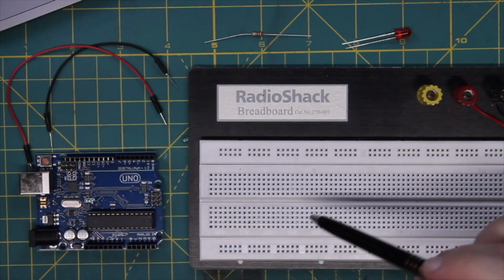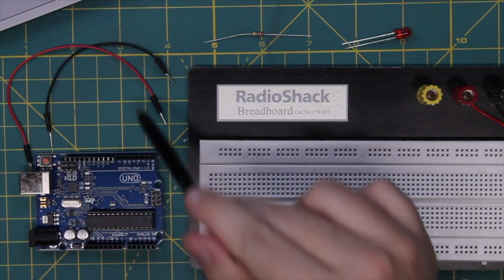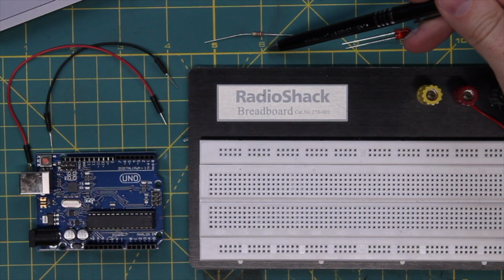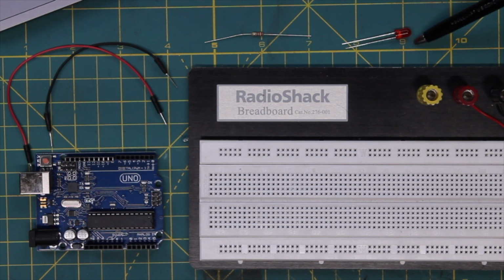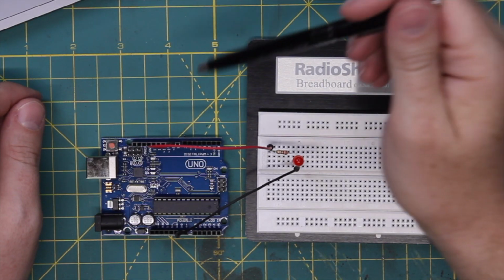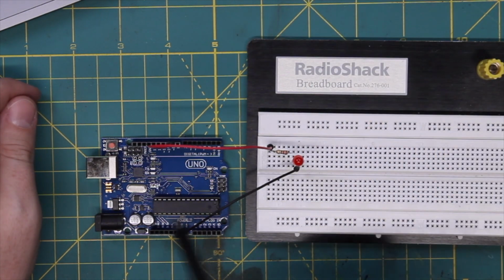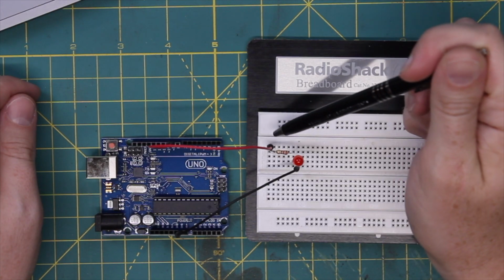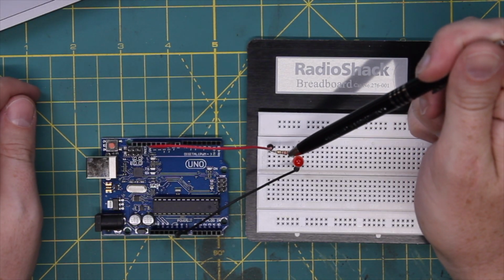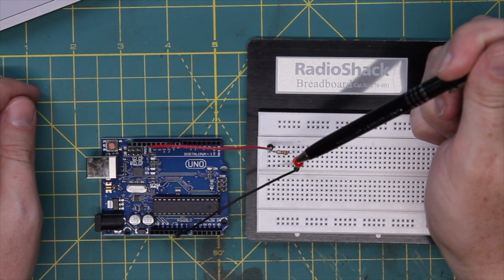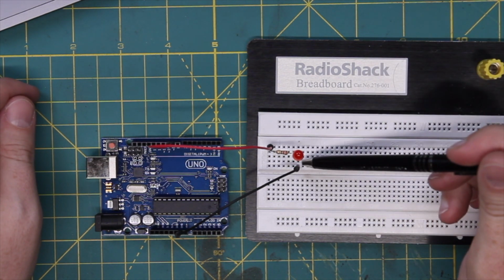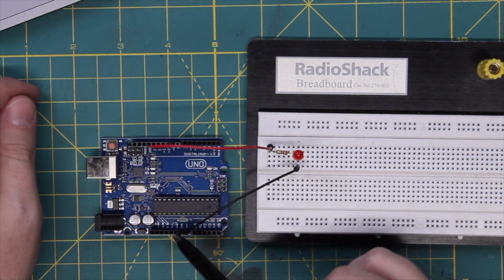Now for this project, we'll of course be using our Arduino, our breadboard, and our computer. We'll also need a couple of jumper wires, a 220 ohm resistor, and an LED. Now, we have a jumper wire coming out of pin 9, which is an analog out pin, as you can see denoted by the little tilde next to the 9, into the breadboard, into a 220 ohm resistor, into the anode on the LED. The cathode then connects to ground via another jumper wire.